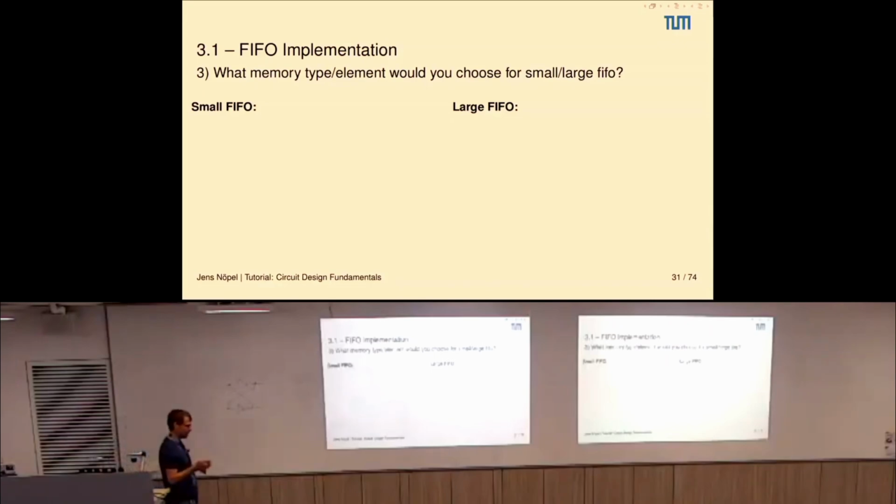So think of it like you have different building blocks. You have latches, and flip-flops, which are built up from latches, right? And you have SRAM cells, which are dedicated memory. The main difference is that SRAM cells are packed in an array manner.